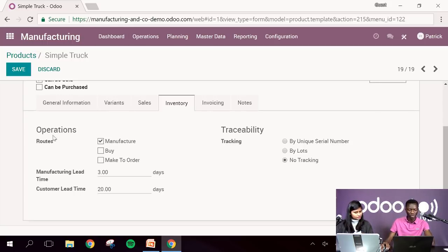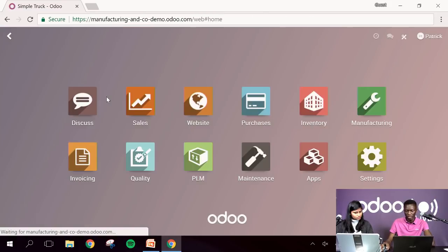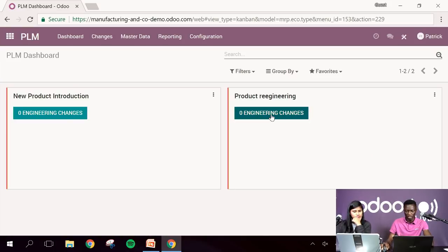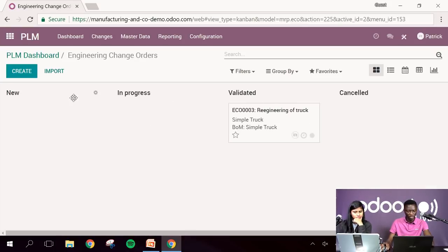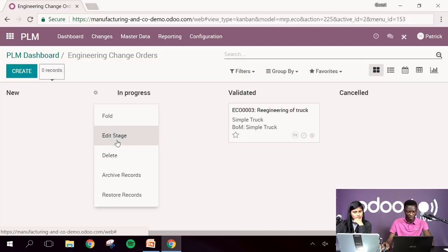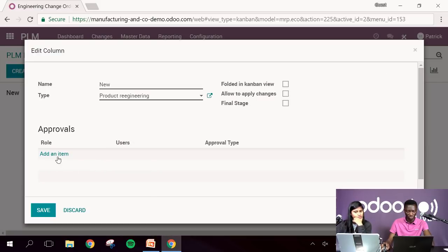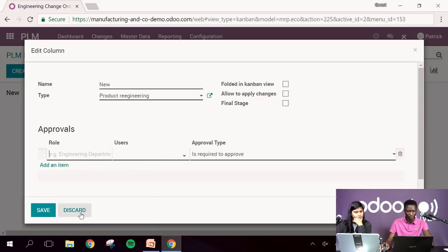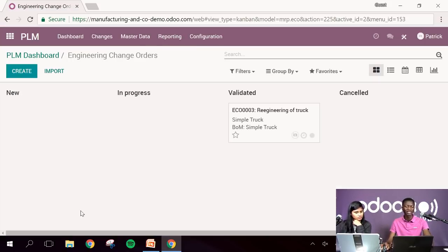Yes, actually, you can do it on every single stage. If I go in PLM, I can take any PLM here. So I can go on every single stage, edit, and say I want to do the approval here. Okay, you set the roles, you define who is going to approve what, or give a comment, and then it will apply for that stage.